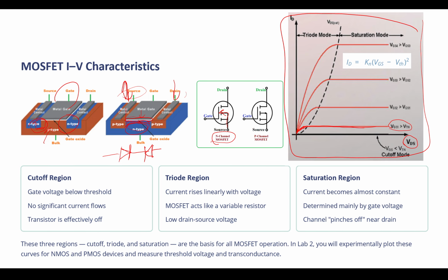Is that statement clear? Any question about that? So based on that, we can say, okay, if I have voltage between gate and source as 0, my semiconductor does not conduct the channel, because I have two opposite way diodes. So I expect to have 0 current regardless of the voltage of the drain and source. Are we good? So we define that as a cutoff region.